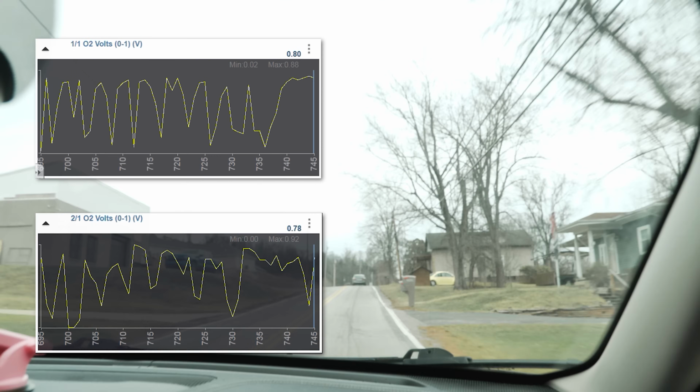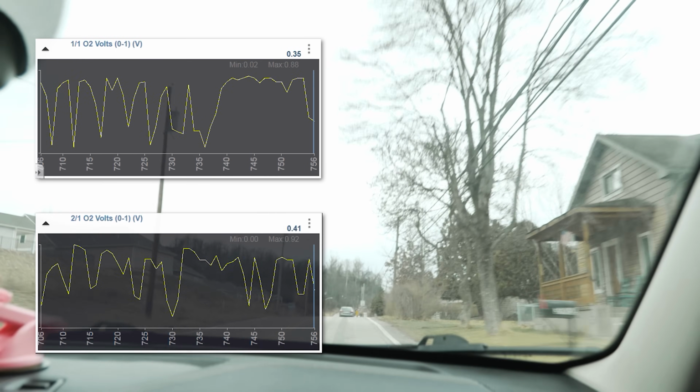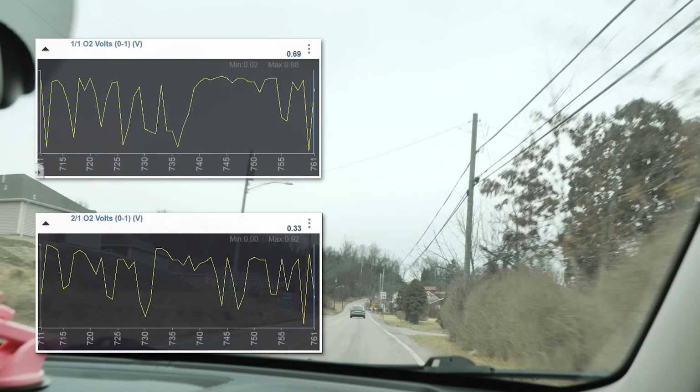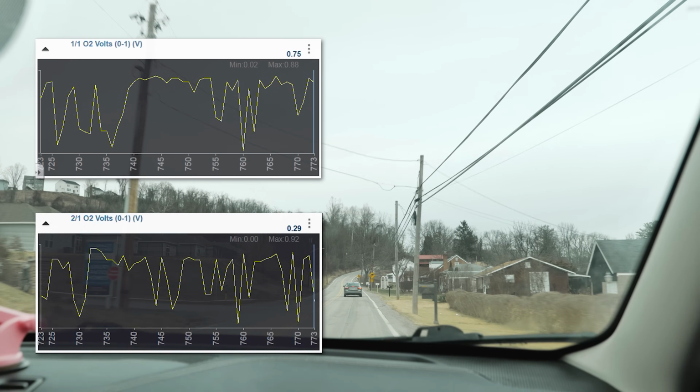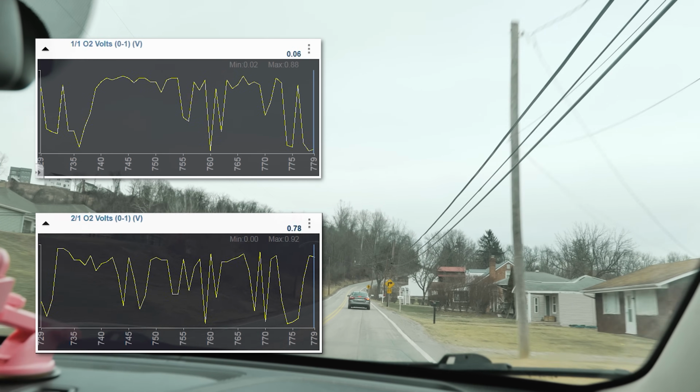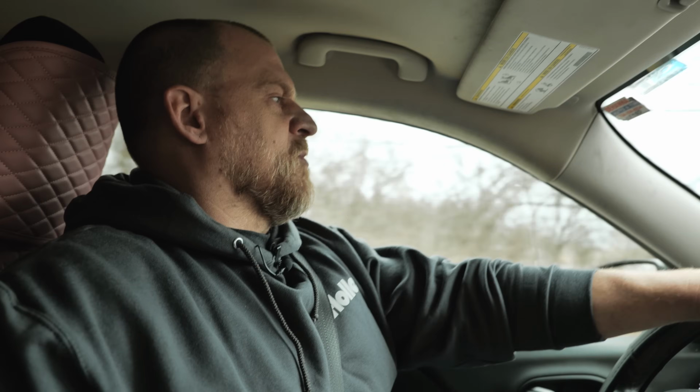and then we're gonna see the short term start to go positive after that. If I can't make this happen, the only other thing we're gonna do today is take a look at that 2.1 oxygen sensor and look at the harness routing and see if we have any rub marks at all where it may be touching ground. Damn. Completely unsuccessful. Visual inspection, and then we're calling it, man.